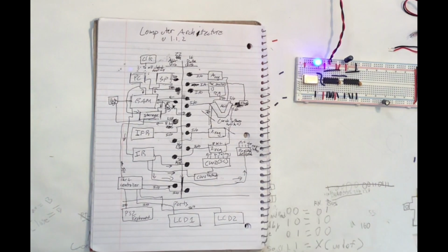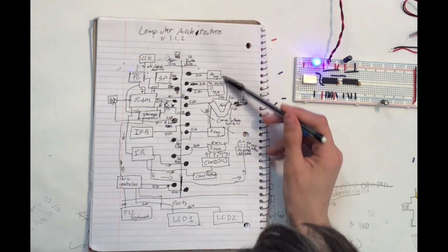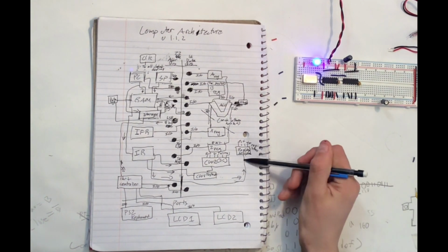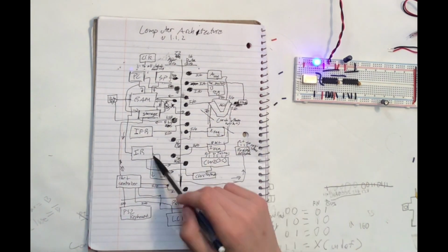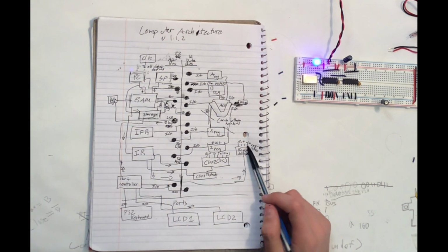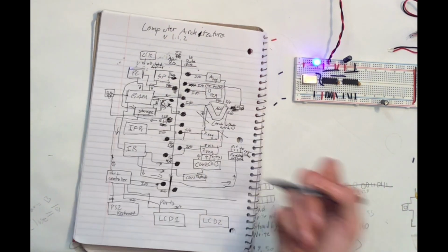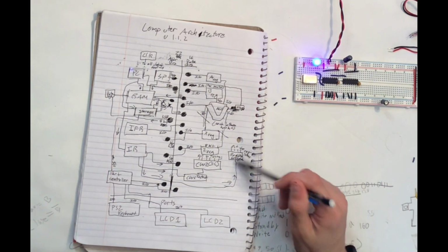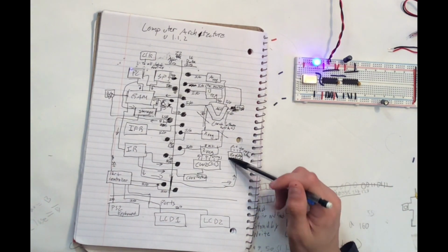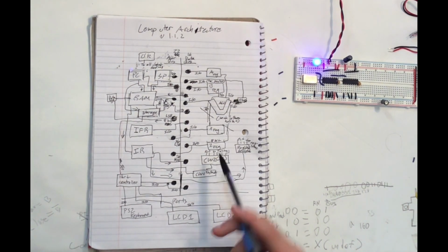So as you can see, this is the block diagram for the computer. We have the ALU, the registers, the register decipherer, which will take part of the instruction stored in the instruction register and tell which register to use. Obviously, the instruction register itself will be connected to the control word because I couldn't decipher it and get that code without the instruction register. So it has to be in the control word. It will also be there.